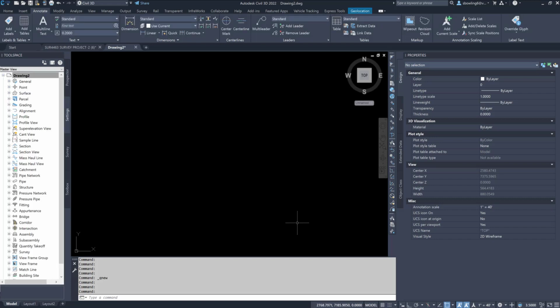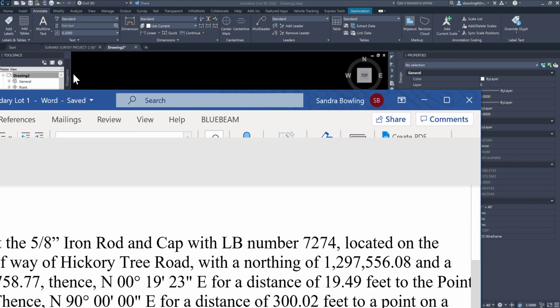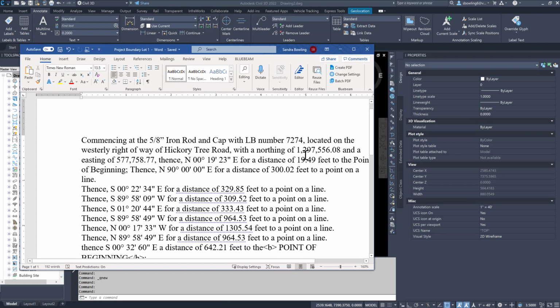Now this is really important to set up the database before you start so you know you're in the right coordinate system. Okay, so if you're looking at this, you're looking at, again, a northing and an easting. Remember that northing is actually the y factor and the easting is the x factor. So I'm going to start out with a line. You have to start the line command from a known point and then use your transparent commands.